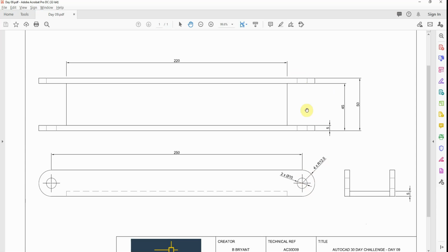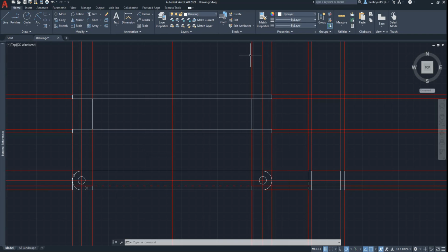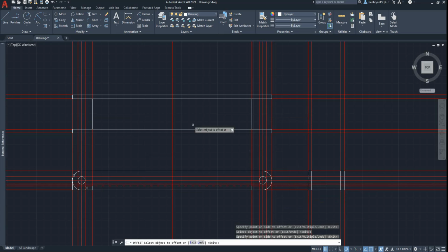What I can do is transpose these sections coming through. So I know there's obviously a hole that will go right sort of through. So again, it's offset in 5mm. It's 5 on the left, 5 on the right, 5 on the left, 5 on the right, and also 5 on the base, 5 on 1. So now what I can do in my hidden tool, come along. Easy what I do is span over both and then trim out afterwards. Like so.